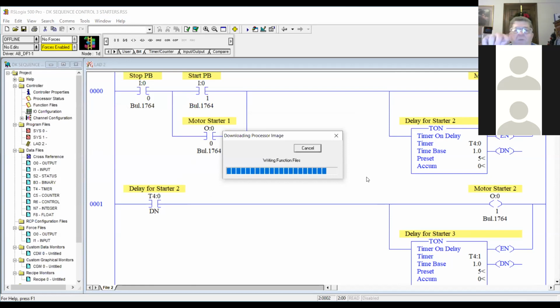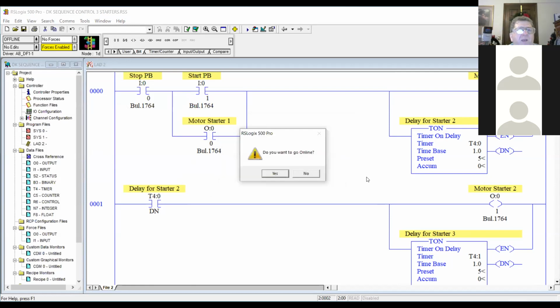So this part is simpler on serial. With Ethernet, you're typically going to have a lot of things to choose from, a lot of IP addresses in a plant, and you've got to be dead sure you point to the right IP because there's going to be a lot of things networked together. With serial PLCs, you don't have that. The PLC is not tied to anything else. It's just a standalone thing, and you can't monitor it from anywhere else unless you've got an adapter.